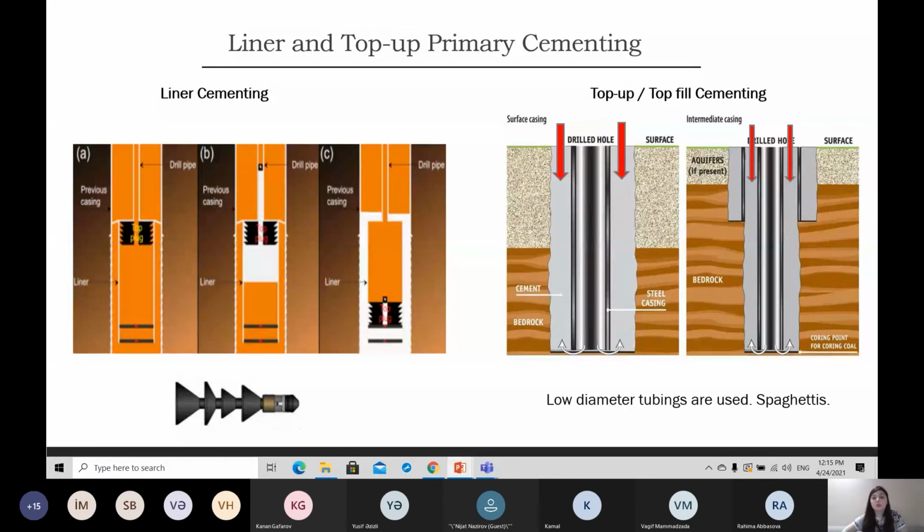And the second technique, to answer the question I got about low circulation in the subsurface, where you don't get top of cement on the surface. You see in the pictures that the top of cement here is at the surface, right? It's still this green zone. However, sometimes the information we get says we are going above the frac gradient and we start to lose everything we are pumping to the formation from these depths. And it means that the slurry will not go up to the surface.